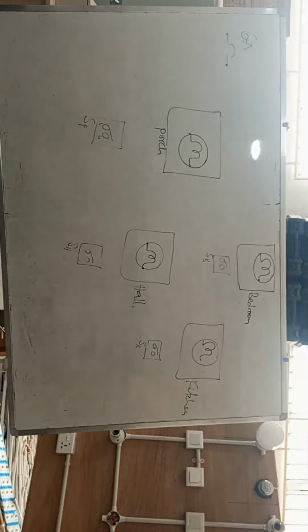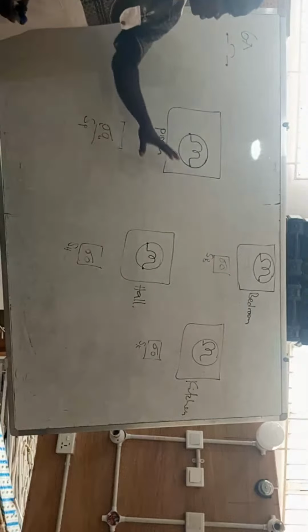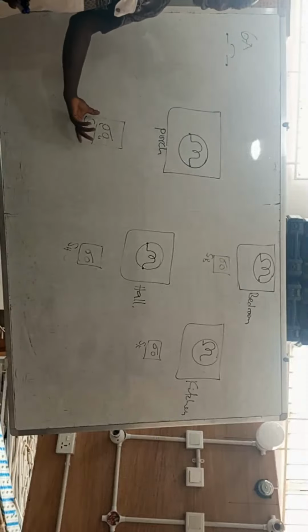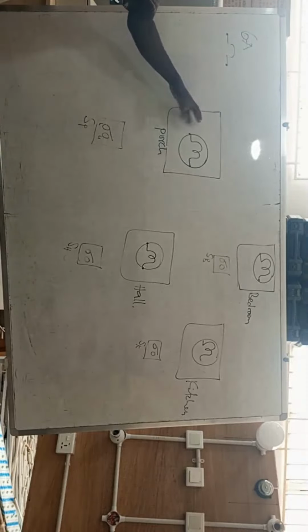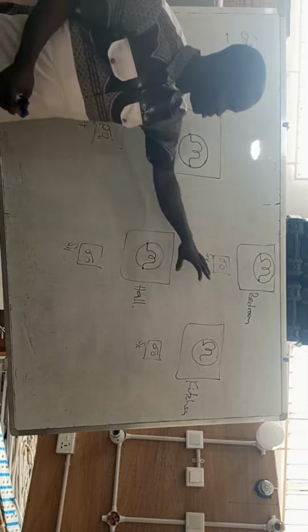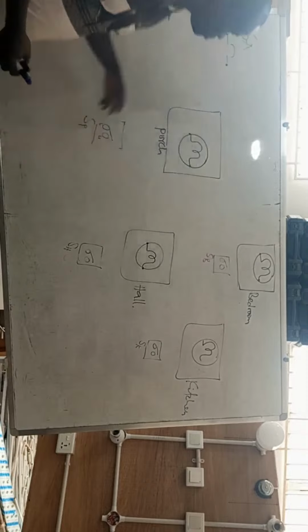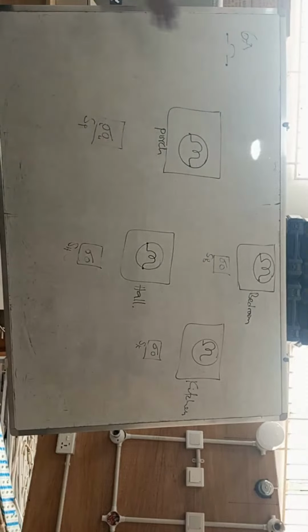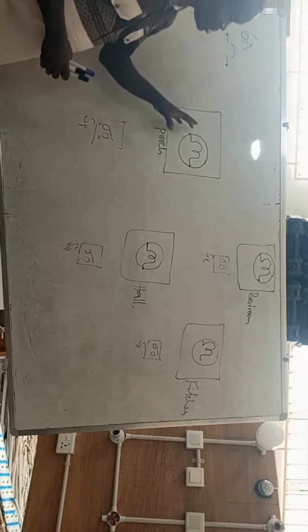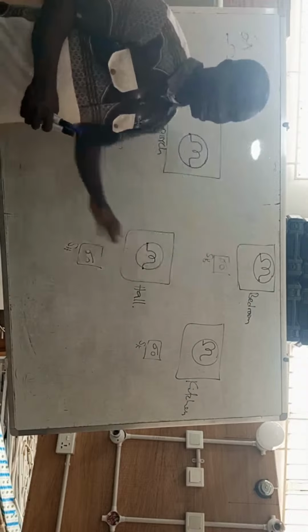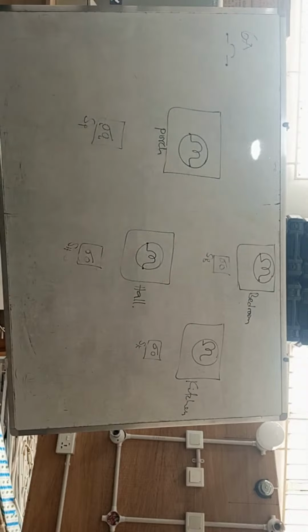Okay. So for our lighting circuit that we want to put on the same breaker, this is what we need. You need a switch, a lamp holder, or the lamp itself, and then a 6-amp breaker. Okay, because we are going to put all these lamps on the same circuit, this is what we have to do.